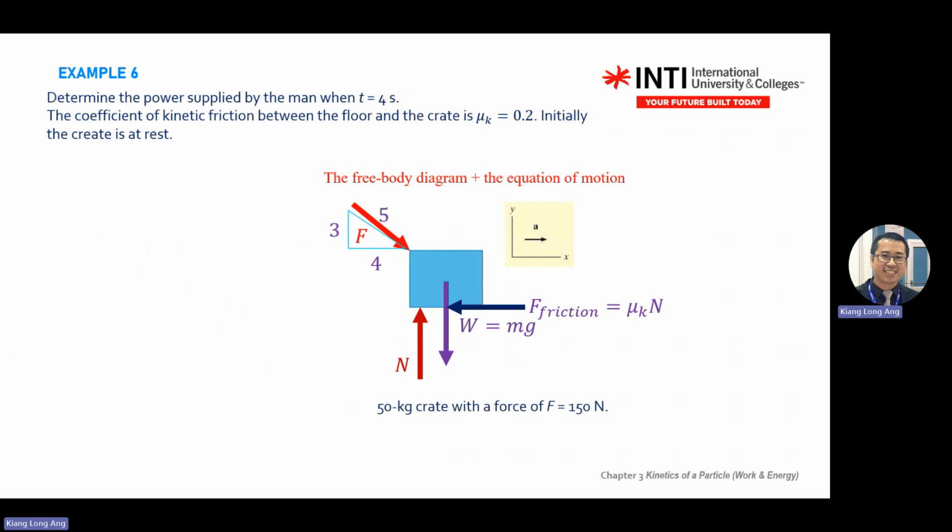Okay. So once you have that, you convert all your force into work. So you do calculation to calculate all the unknowns first. You don't know your n, so you need to do calculation for n. So how do you do calculation for n? Go back to chapter 2, same procedure. You write F equal to ma to find the n.